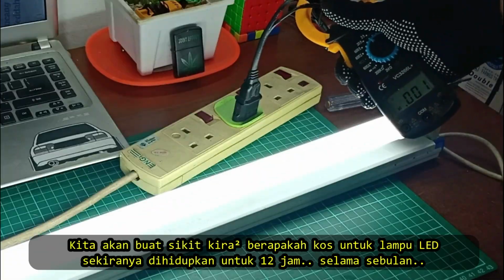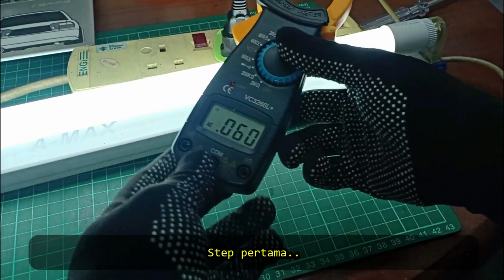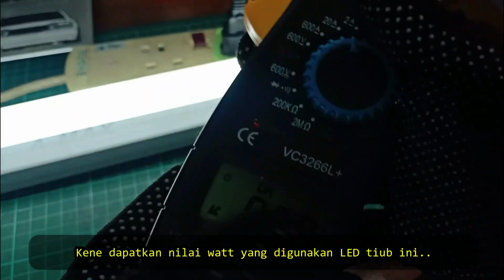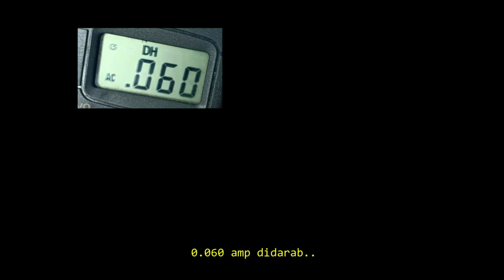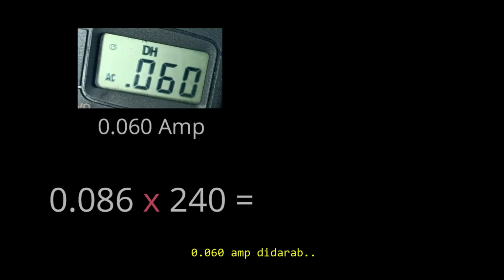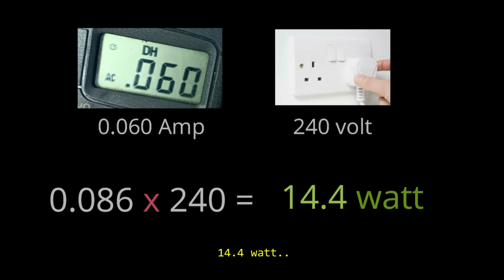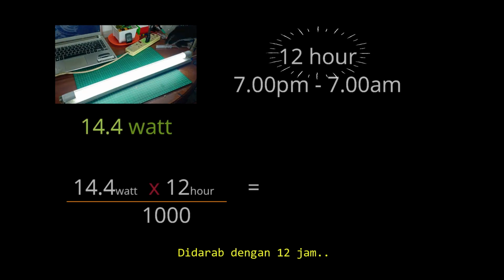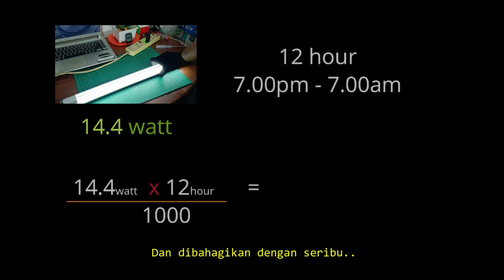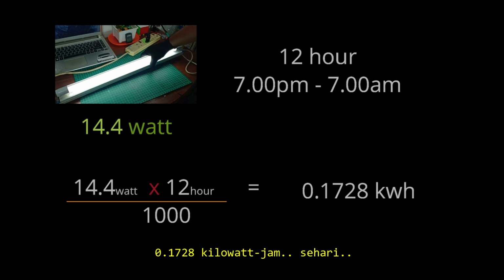Now, we are going to calculate cost using LED tube for 12 hours. As usual, find the total wattage of the LED tubes. The current or amp reading is 0.060. 0.060 amps multiplied 240 volts equals 14.4 watts. 14.4 watts multiplied by 12 hours and divided by 1000 equals 0.1728 kilowatt hours.